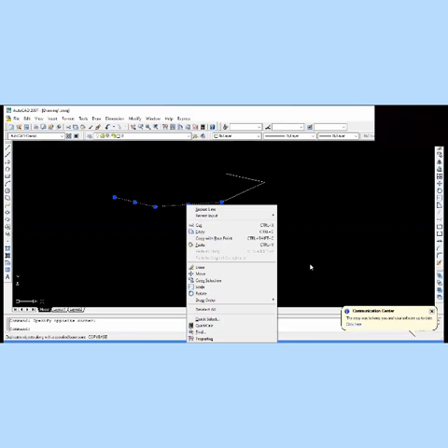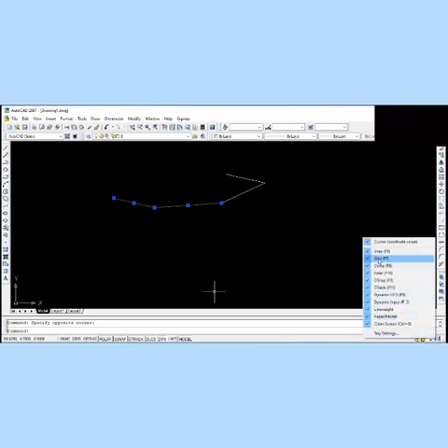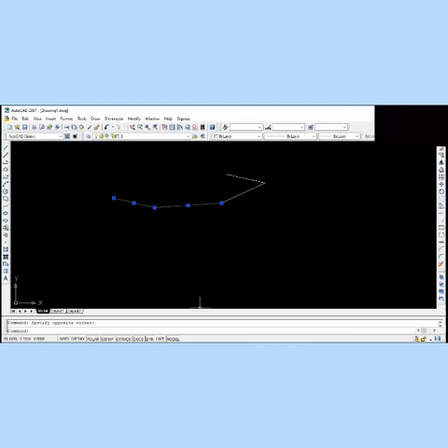So now, you can control the display of buttons on your status bar. You have snap grid and all this. If you don't want these icons to show here, there's a way you can control it. All you need to do is come to this place, or you right-click on this. Once you right-click on this, you select or you clear. Once you clear, if you don't want snap, you notice that your snap is no more here.